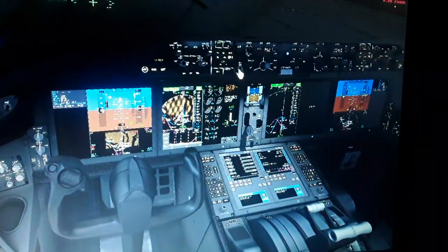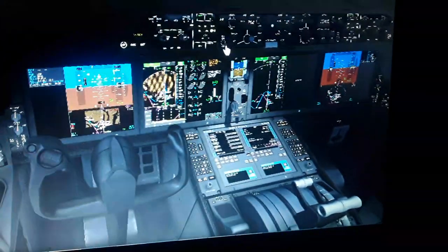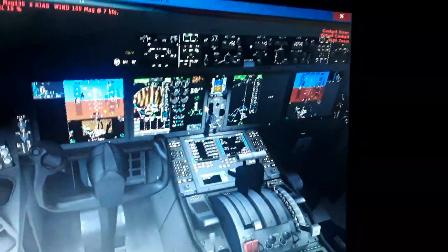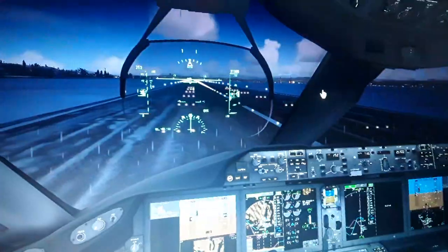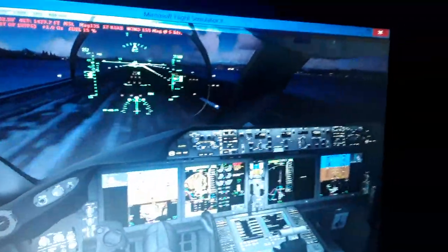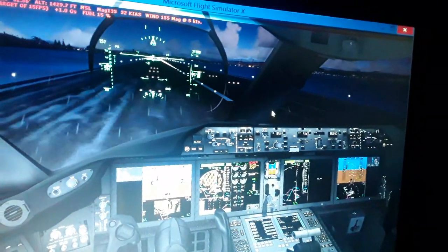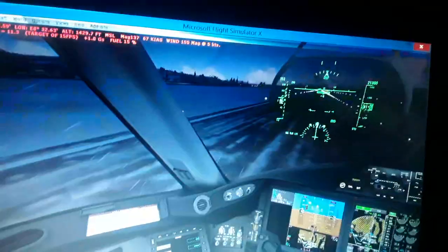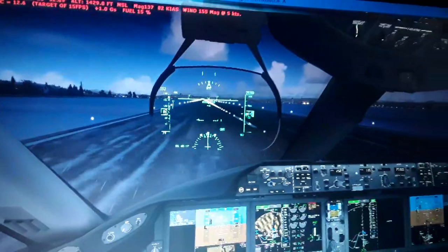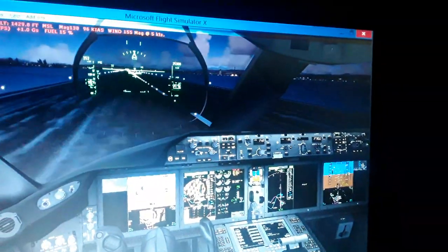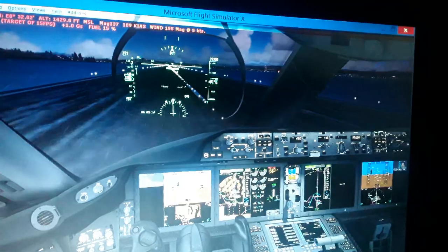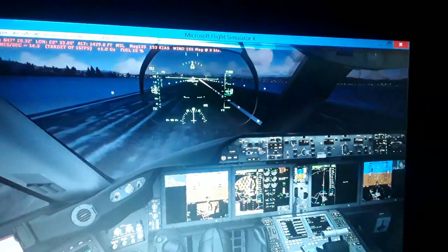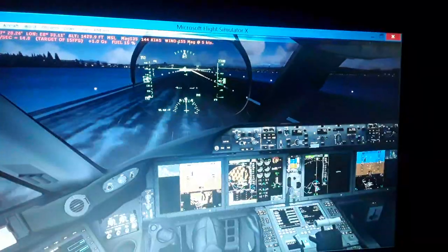Perhaps advance the thrust levers. I'm not sure. And go. So parking brakes are released. So we align with the rudder pedals with the runway. We have 90 knots. Use the rudder pedals for alignment. 100, 90. V1, we rotate. So we rotate slightly.